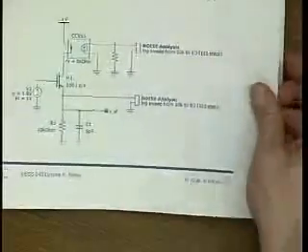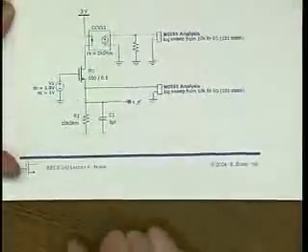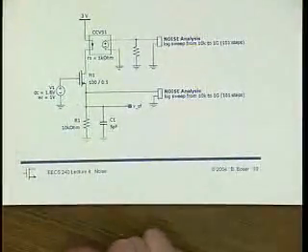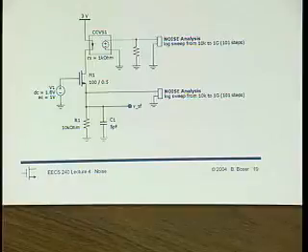Okay. There is one more thing that I want to just point out, and there is also an example in the notes on that. When we calculate input-referred noise, even though we want to know the noise at the input of our circuit, we have to determine what is the output of the circuit.